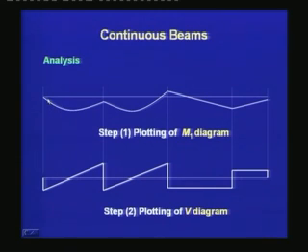It follows the same characteristics, that means it goes down in the end span, again it comes up near the end support, and again it goes down at the intermediate span, and then it goes above the reference line at the support, and it follows the trend of the profile of the CGS. This M1 diagram is calculated from the relationship M1 is equal to PE times the eccentricity.